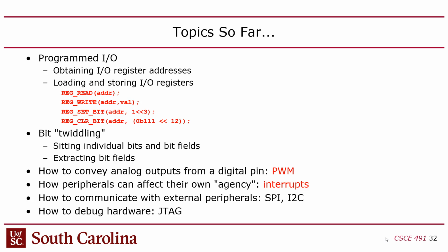Well, actually, this includes the read part. So included in these intrinsics, you read the old value of the I/O register based on its address, and then you manipulate a bit field, and then you write it back. So all of that functionality is included in these 2 intrinsics, but you have to still do the shifting part.